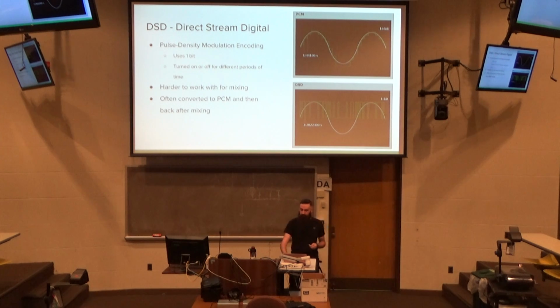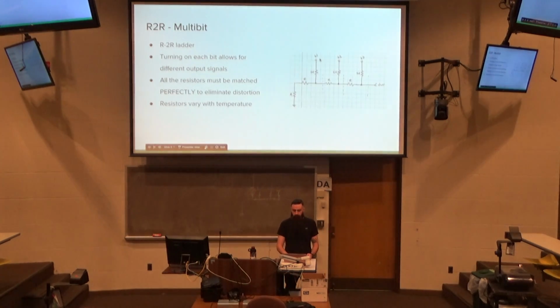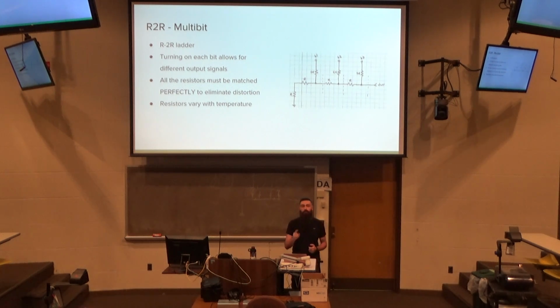So you need the ability to change the numbers really fast, which are being output to the bits, and you need the ability to then have a very accurate set of resistors that make it so that each one of these bits is applying exactly the right amount of current. So the reason that these aren't used is because they're very expensive and difficult to source.